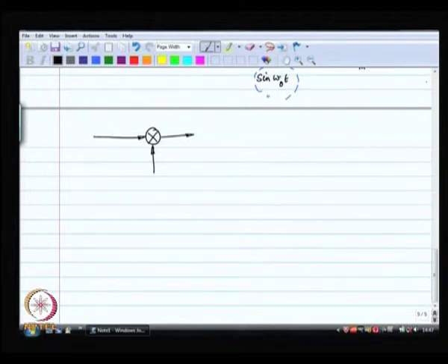However, your definition of a second is different from my definition of a second, because we are not on the same chip, right. The transmitter, the base station, is somewhere and the receiver, the handset, is somewhere else far away from the base station. So the handset has no idea of what the base station means when it says 1.254 gigahertz, right.